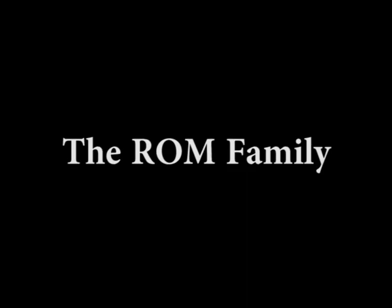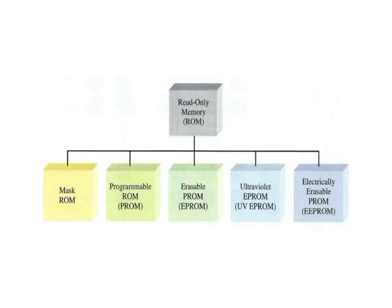The ROM family. Figure shows how semiconductor ROMs are categorized. The mask ROM is the type in which the data are permanently stored in the memory during the manufacturing process. The PROM or programmable ROM is the type in which the data are electrically stored by the user with the aid of specialized equipment. Both the mask ROM and the PROM can be of either MOS or bipolar technology.